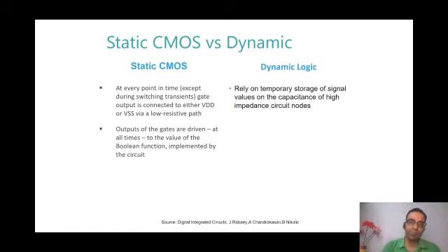We'll be changing our output position regarding that. The main issue with this dynamic logic is that, okay, the advantage is that area gets reduced at first, and the issue is that we'll have some race around conditions and cascading conditions. Okay, so we'll look into much more detail in dynamic logic later. Whenever we call something dynamic, whether it is a memory cell, for example, if it's a static memory, then you have a 6-transistor memory cell.